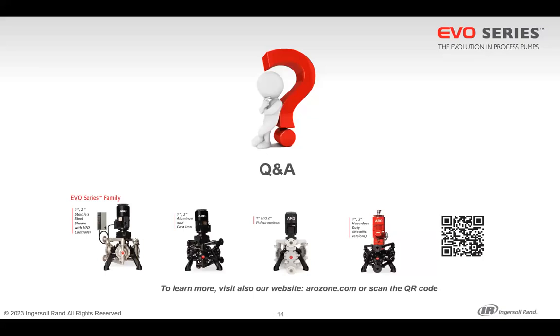Yeah, good point. So there are a couple of things that we should say here. First, in terms of humidity control inside the air chamber, no, there is not. The only way to control the humidity inside the chamber is to inject dry air to the inlet manifold. So that's why the customer in this particular situation is injecting dry nitrogen.